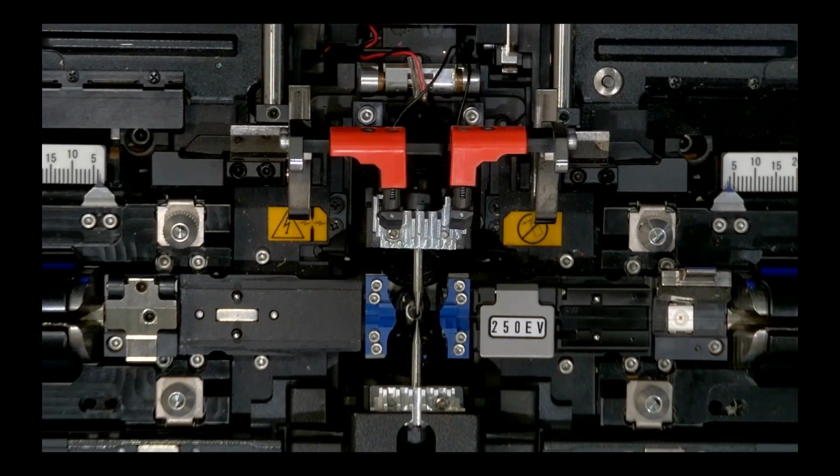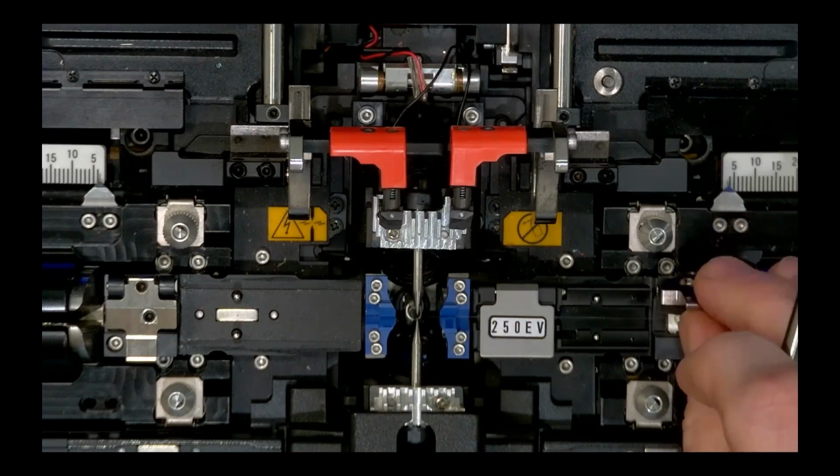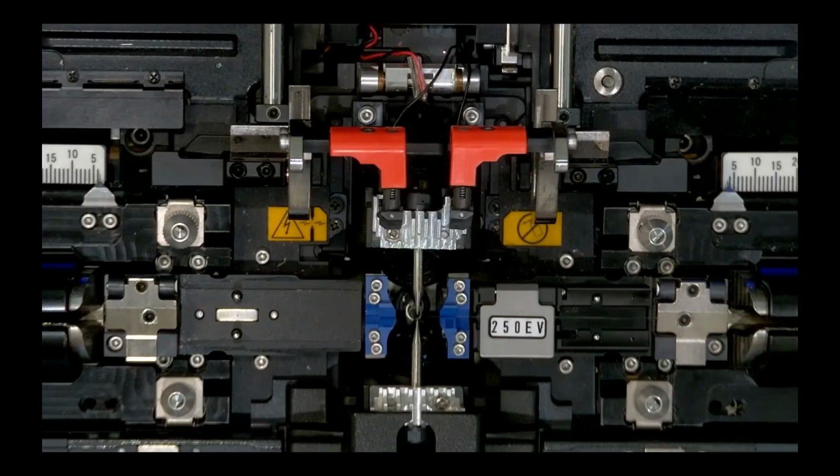And so this is where a fiber holder normally would sit, right? Now with larger diameters, we generally recommend up to like 250 microns and larger that the fiber holder actually be loaded the other way. However, on the Plus models, that's not so much of a requirement, right? Because not only would that mean you have to remove the LED unit, right? But the reason it's not a requirement is because you have the additional capability of this Z stage adjustment, right?